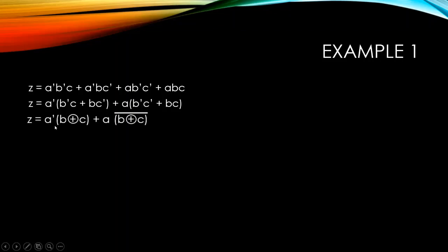And by rewriting it using XOR and XNOR, the equation inside the parentheses, okay? So in this equation, we could see that it's also another XOR. So therefore, we could rewrite it as A XOR B XOR C. So by using our knowledge about XOR and XNOR, we simplified it from four terms with three variables, now three terms with one variable for each term.